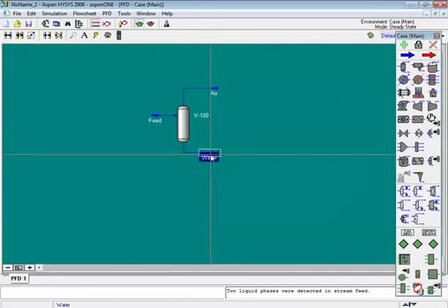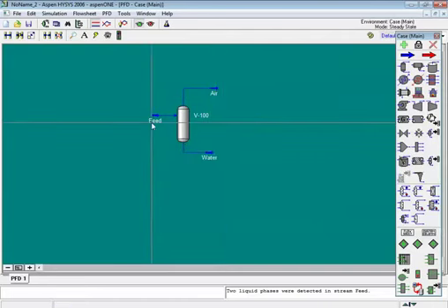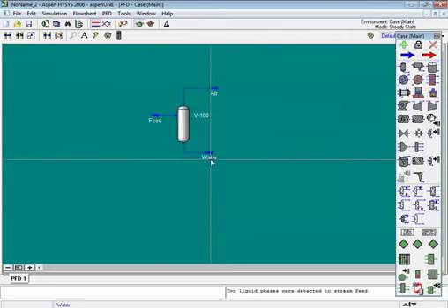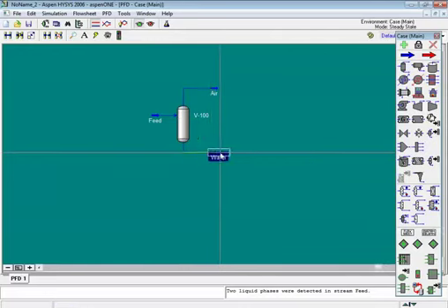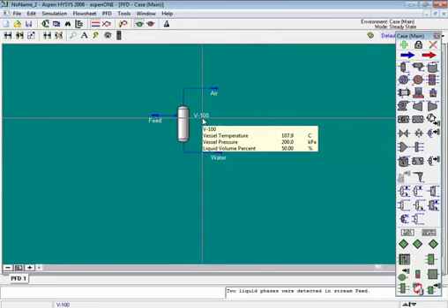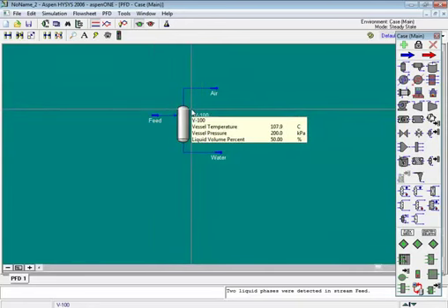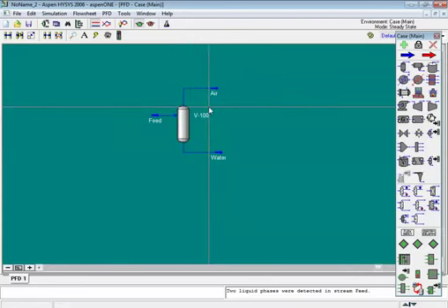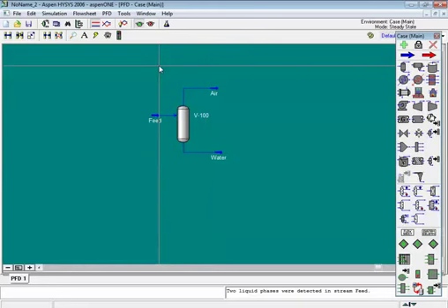For dynamic simulation, we first need the valves. There should be valves in and out where we can do the control. Every system interface should have some valve. For a simple system like this, it will not add the valve, we can add it ourselves. But for a larger system, sometimes the dynamic assistant itself adjusts the valves, or we have to put the valve.